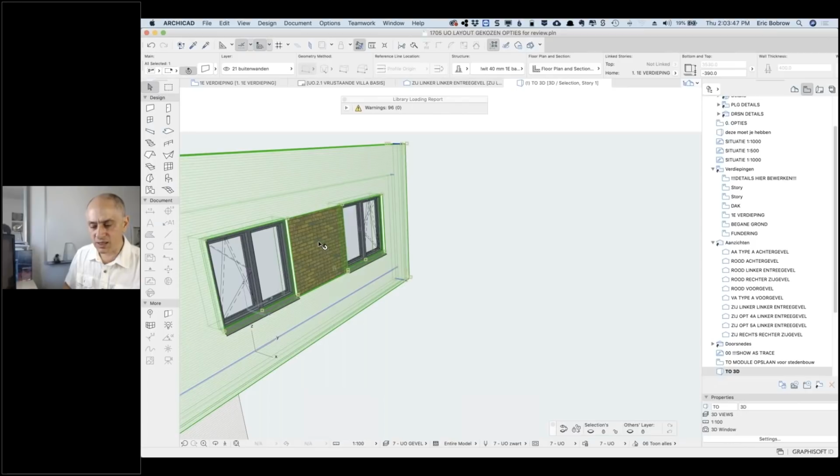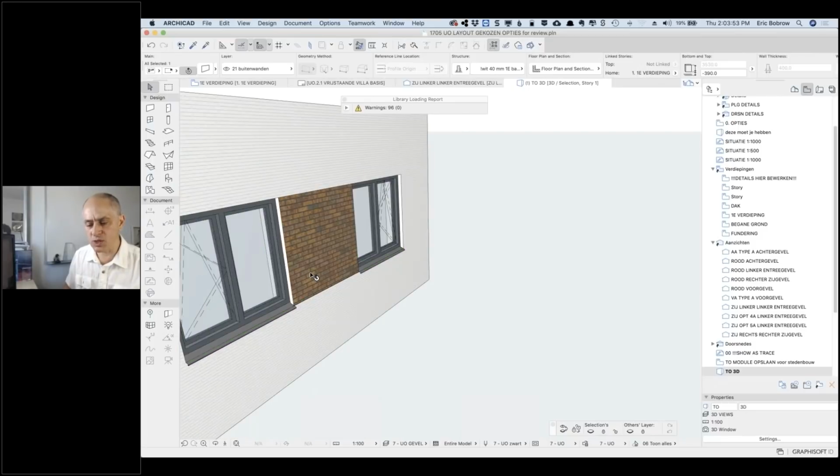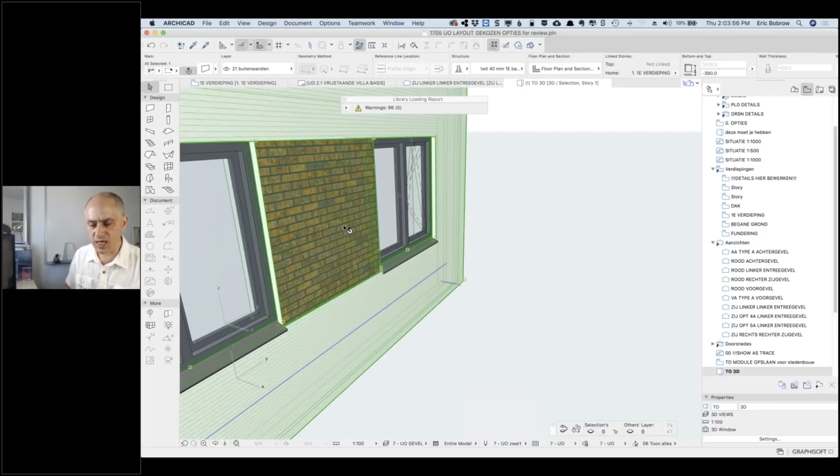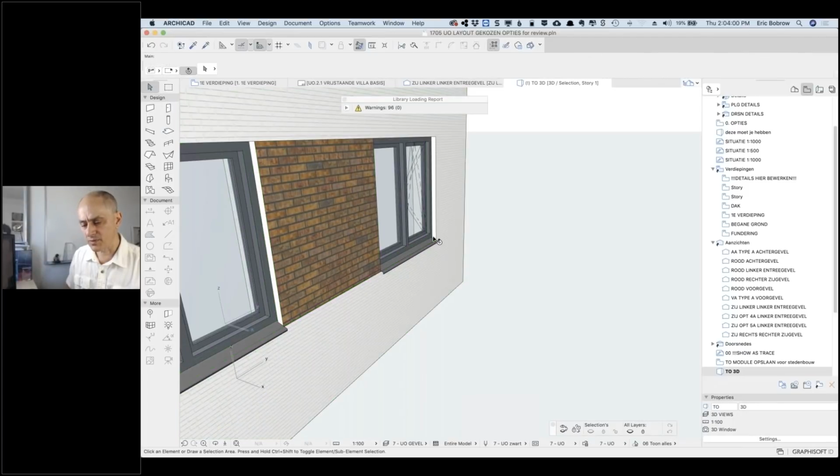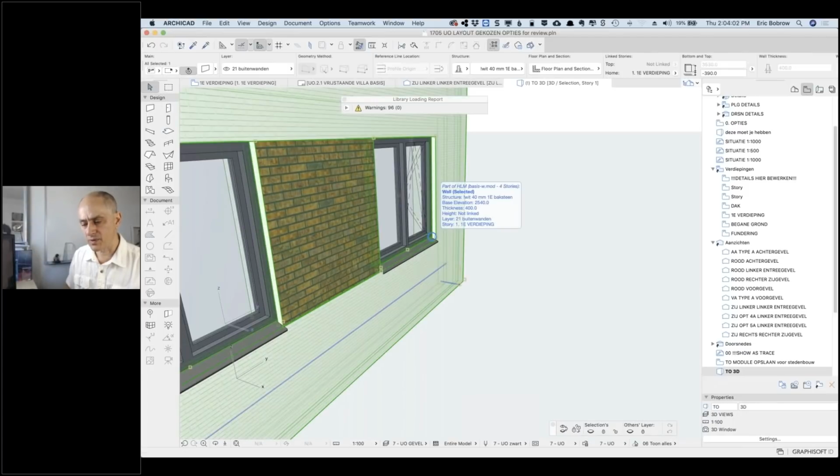When I click on this, it looks like it's all part of the same wall. So tell me how this was handled to get the different material in there. There's a window, and it's not actually a window. It just breaks a hole in the wall, and you can offset it by a little and say it has to have another surface.